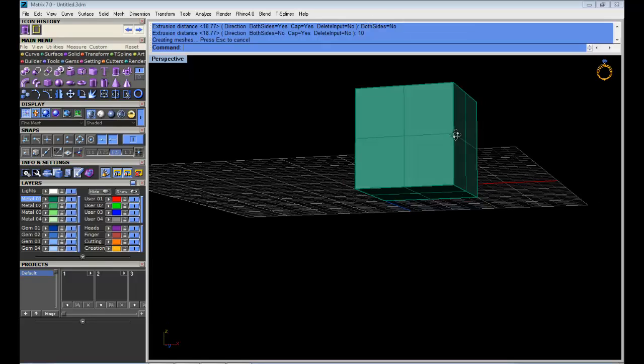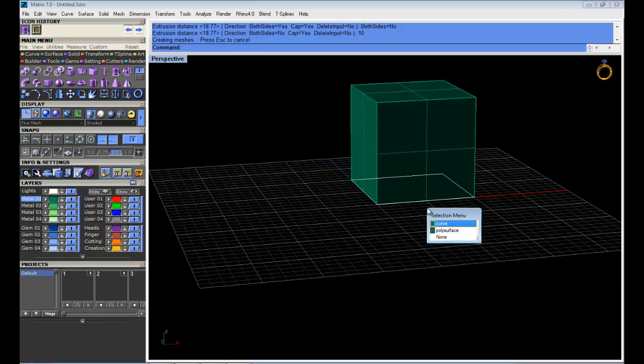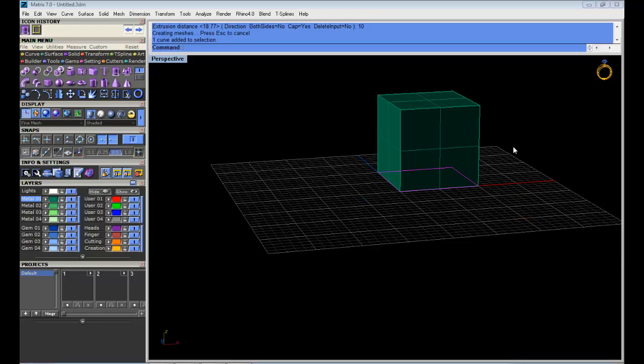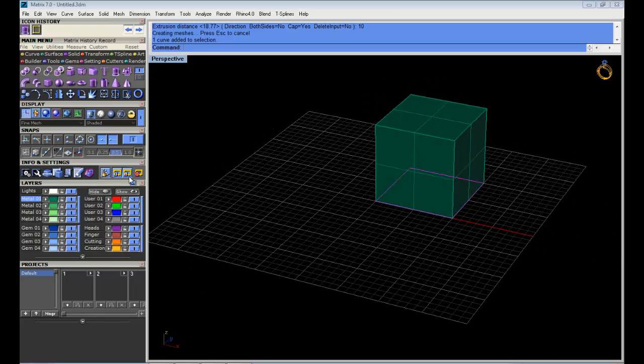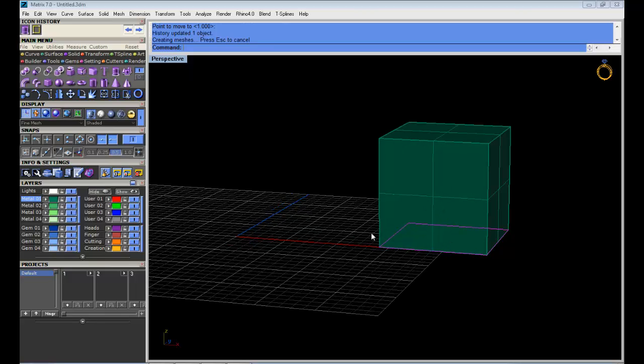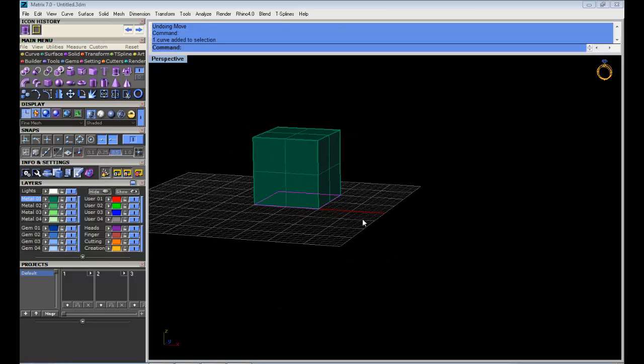Now we need to select this line in here. We can click on the edge, left click in here on the edge, or we can drag a window from left to right, just selecting the actual curve. Mind that in my case, these three buttons were activated, were checked. That is the history. The moment I select that curve and move it to the side, you see that everything gets updated. We don't want that to happen, so we need to go backwards, delete these three, and move again.